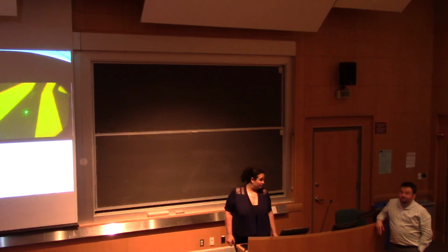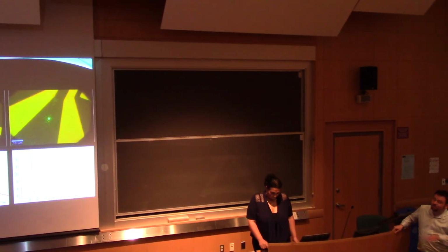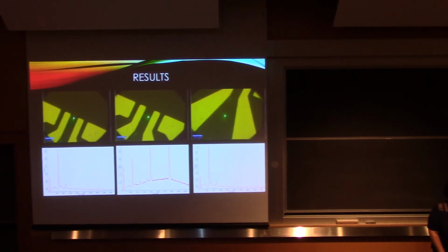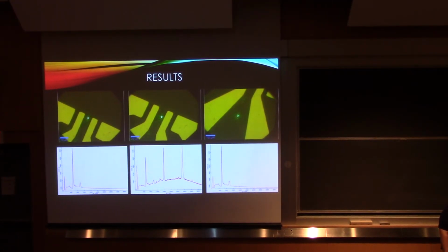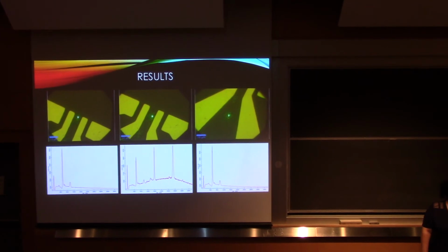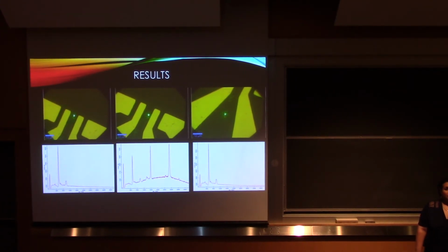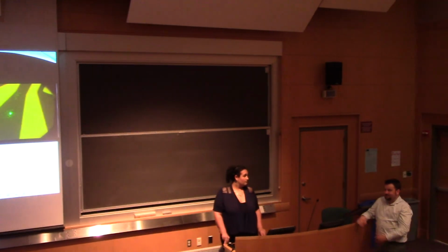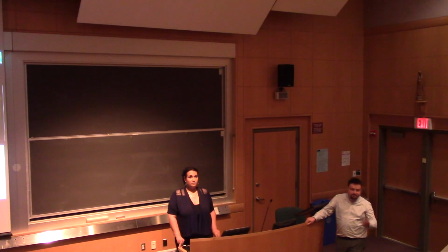So there's no fluidic there yet. What you see are the 4 gold contacts. The purpose is that you can put current through 2 of them, the ones on the outside, and measure the voltage drop on the ones on the inside. The main reason is that in previous studies, people only did 2, so you never know exactly what the contact is doing from the graphene. When you have 4, you can separate out your contact from the graphene, but it means the fabrication is much harder, hence her work to get it right.